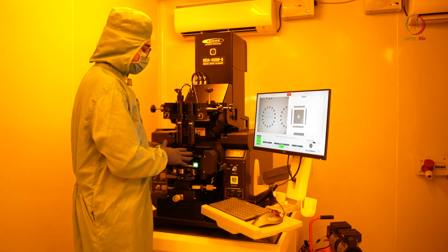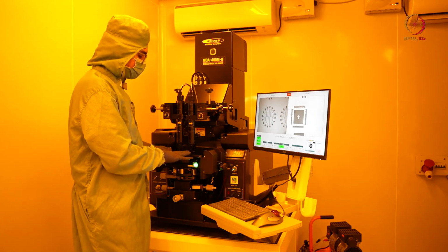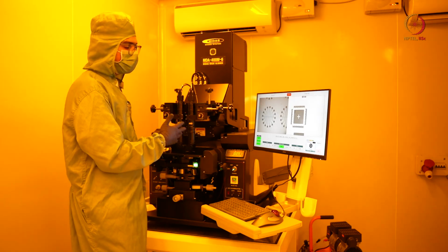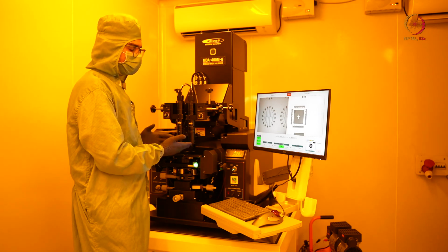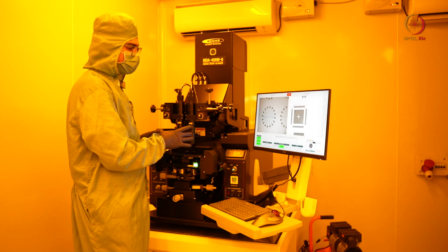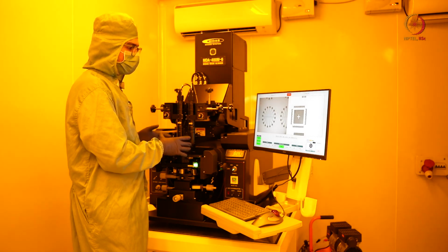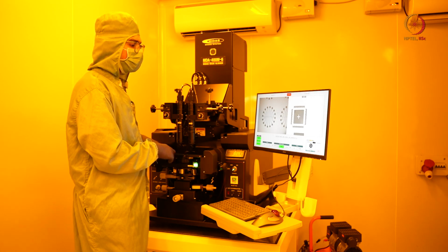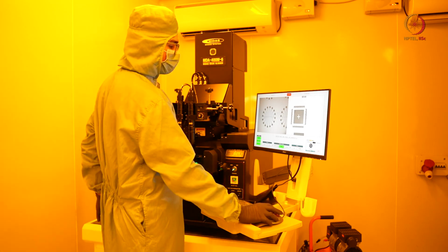But yeah, so now we have the wafer and the mask aligned. Since this is a first mask process, we don't have an alignment process as such, but we just have made sure that the wafer is sitting almost on top of the mask, almost aligned with the wafer that we have. Now the next step is to go for exposure.